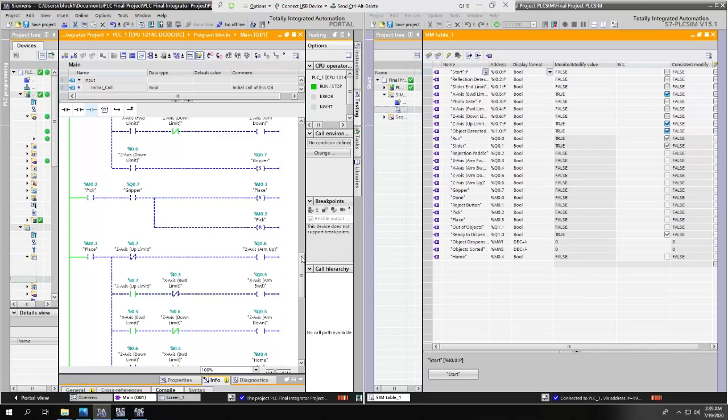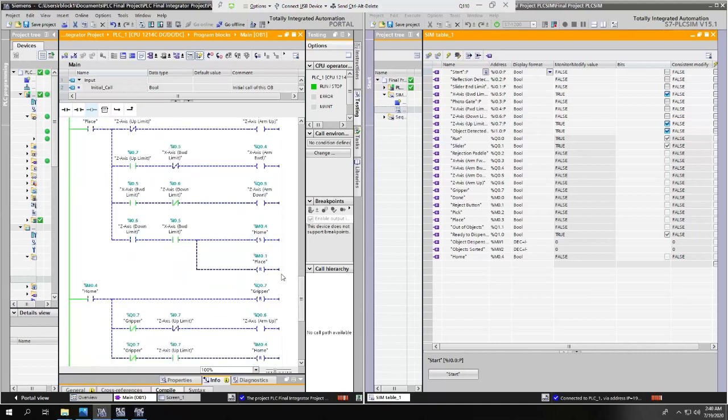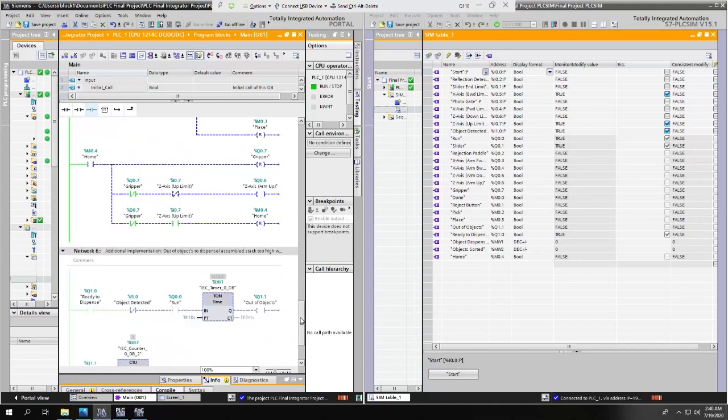the pick process, going to the next section of movements, in which the arm goes up, back to this home position, goes down, and goes into the place process, which resets the home process. There it will open the gripper, dropping the object, and return back up after resetting home, meaning that the arm process has been done and the object has been moved from the assembly line drop-off area into the assembly area.